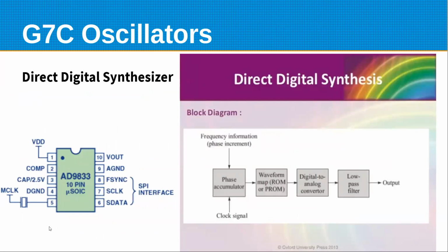This is a typical little integrated circuit that does all this stuff in this little 10-pin package. It has this first stage, which they call a phase accumulator, fed by a high frequency clock.